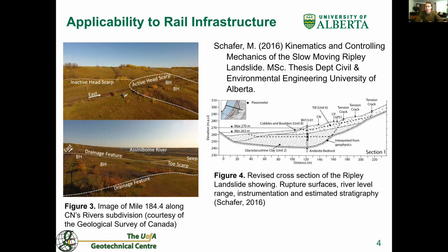Our current understanding of heavily overconsolidated clay or shales is that they have a dilative response, which leads to a decrease in pore pressure during shearing. This decrease in pore pressure would then lead to an increase in shear strength. Our work hypothesizes that this fundamental understanding may be overestimating the capacity of these slopes to short-term undrained shearing events when strain-controlled boundary conditions exist.